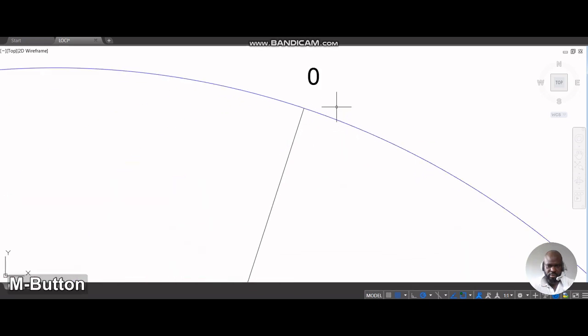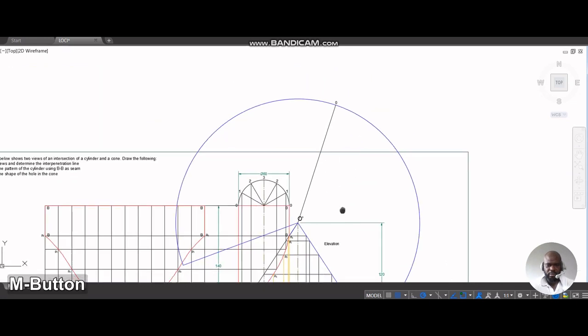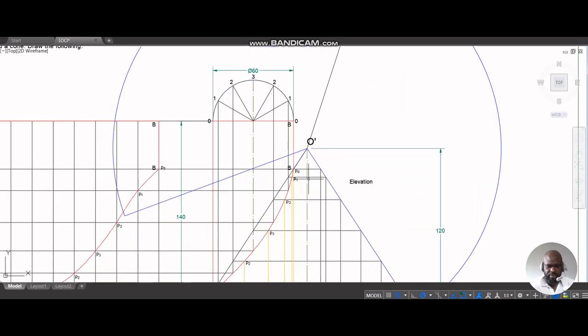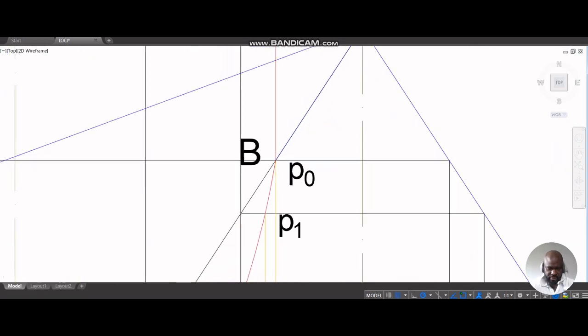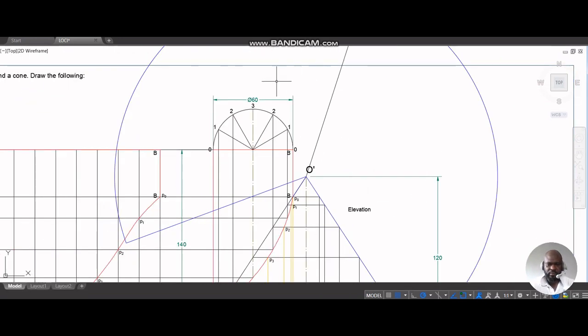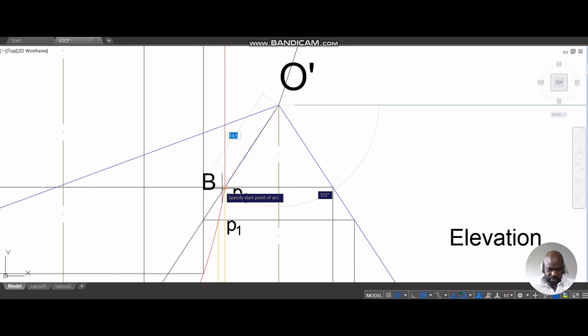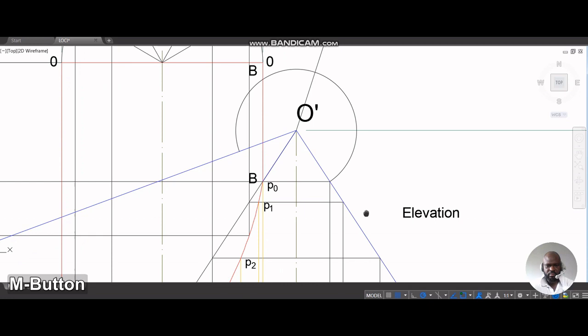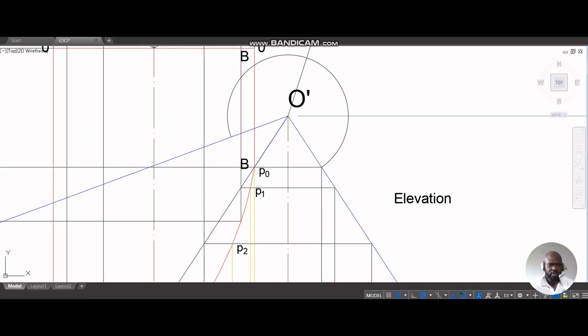All right, let's say this is point 0. This is our reference point now. With that as our reference point, we are going to draw construction lines for each of those points on the curve through the development of the cone that we have. This is what I mean. Pick your compass, extend to P0. P0 has an address here, so we'll draw a curve.